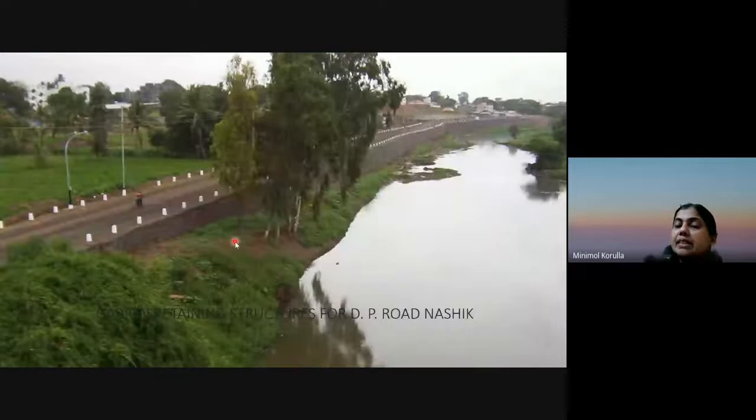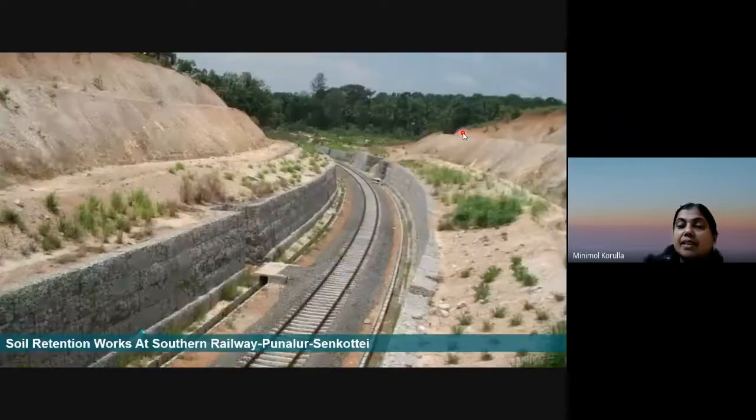This is DP Road, Nasik. Again, this is a black cotton soil which has swelling characteristics. Usually, if you go for a normal concrete structure in a black cotton soil, it will generate a lot of cracks. But when we go for this type of flexible structure, it can accommodate the swelling or settlement to a great extent. It also has its own limits, but it can accommodate a lot of differential settlements and swelling.